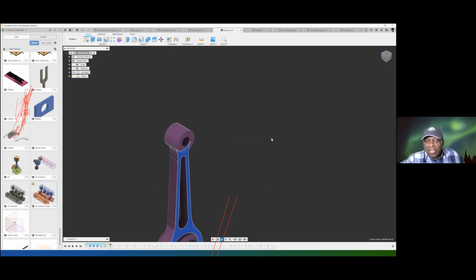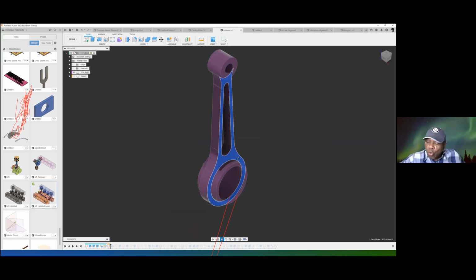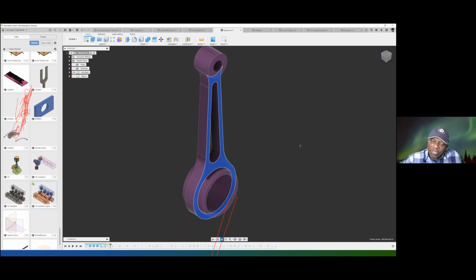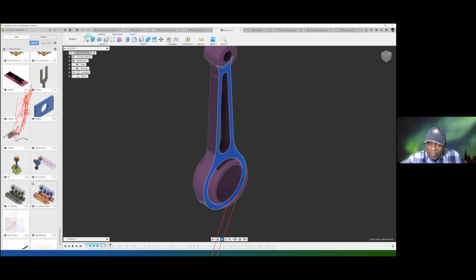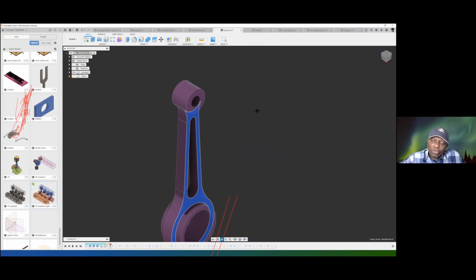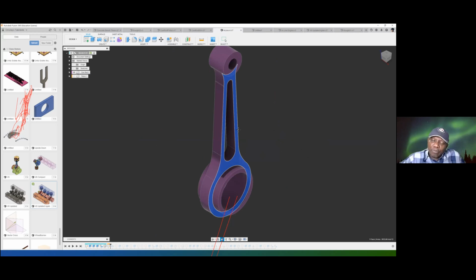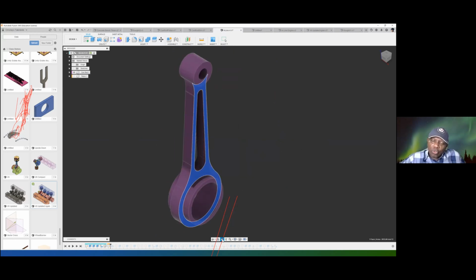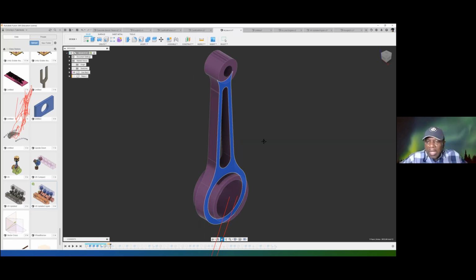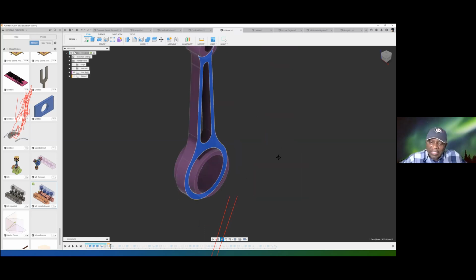But that is not the only way to pan. You can also hold down your mouse wheel, and it will invoke that pan automatically. Just by holding down my mouse wheel, you can see that the hand sign on the pan turns blue. So you can either do it by clicking here and pressing the right mouse button, or you can leave it alone and just hold down the wheel button. It will achieve the same thing.